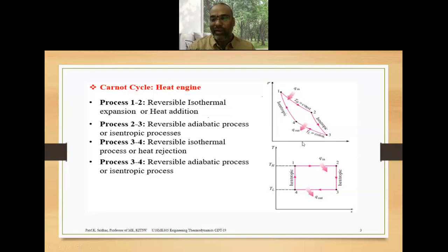It is easier to remember than on the PV diagram, because on the PV diagram you can see so many curved lines. With four different curved lines, it is very difficult to remember the Carnot cycle on the PV diagram. That's why I suggest you remember the Carnot cycle on the TS diagram, because it is simply a rectangular box. It is a rectangular box because 1 to 2 is a horizontal line. The horizontal line on the TS diagram represents a constant temperature process.